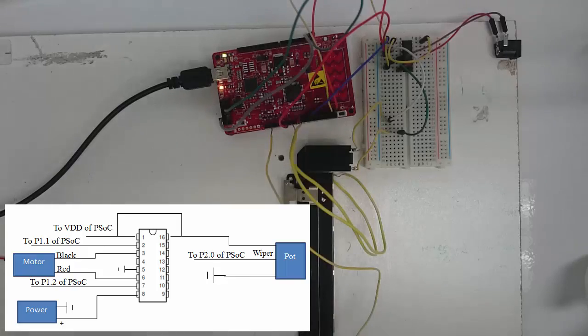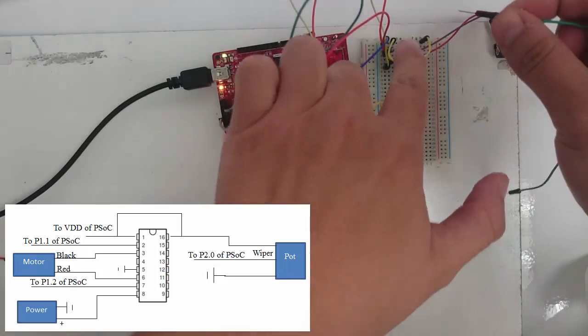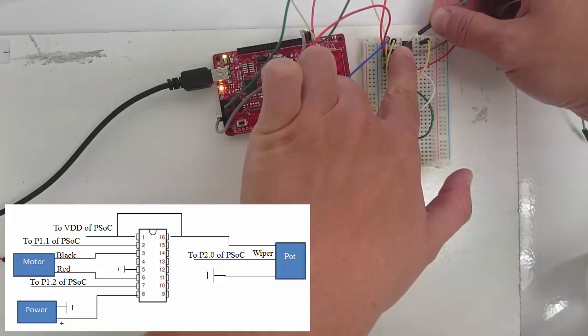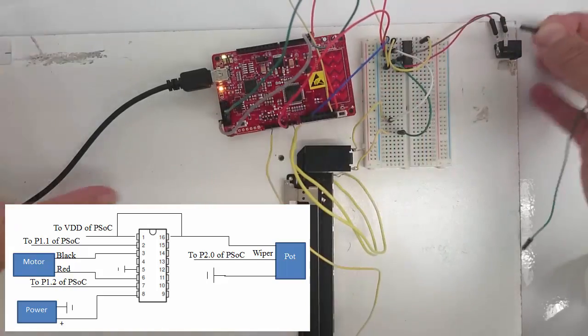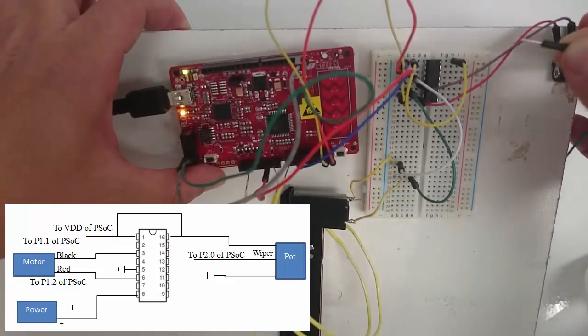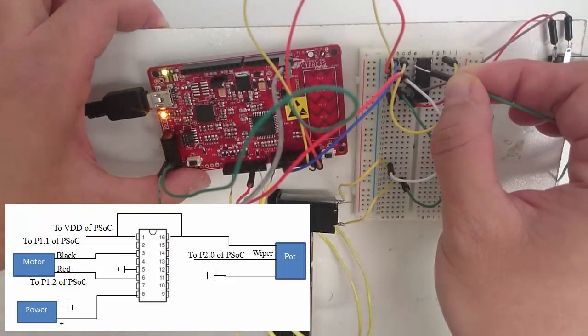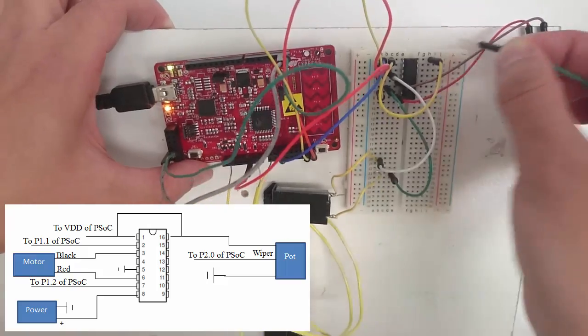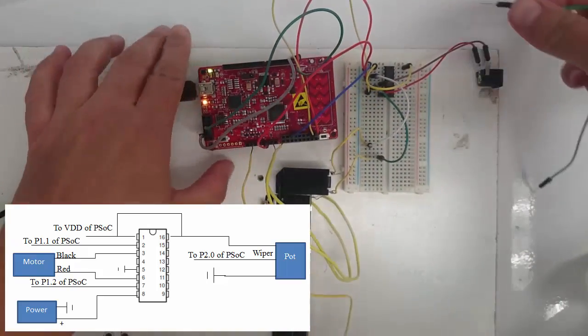First of all, the chip connections should be like this. Make sure to start out by finding the top of your chip. Remember that the top of the chip is the part that has this indentation at the top. It's like a half circle and it's indented.